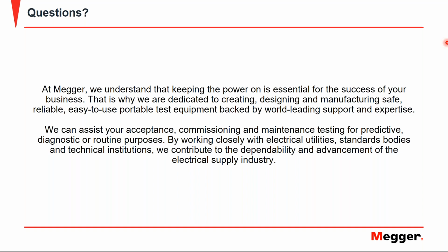Let me start with standards. If you look to PD, there is a standard for how to describe or how to measure PD, what failures you can detect, and what inception and extinction voltage is, but there is no standard yet which gives any trending limits for on-site field testing for PD diagnostics.